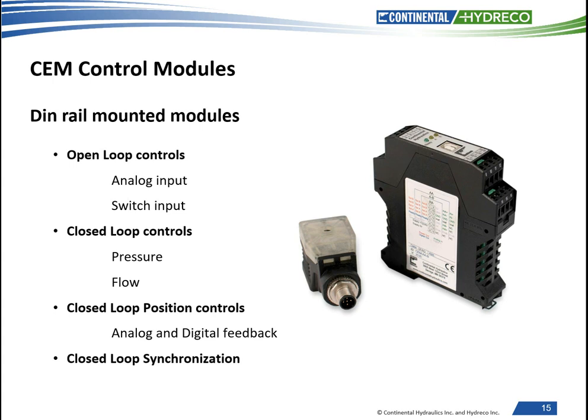With that particular card, the analog feedback devices each go into this card, and the error between those two tells a small valve to either add flow or subtract flow. Actually, it adds and subtracts flow at the same time, synchronizing, making it a very economical type system. So we do have some unique products there as well.